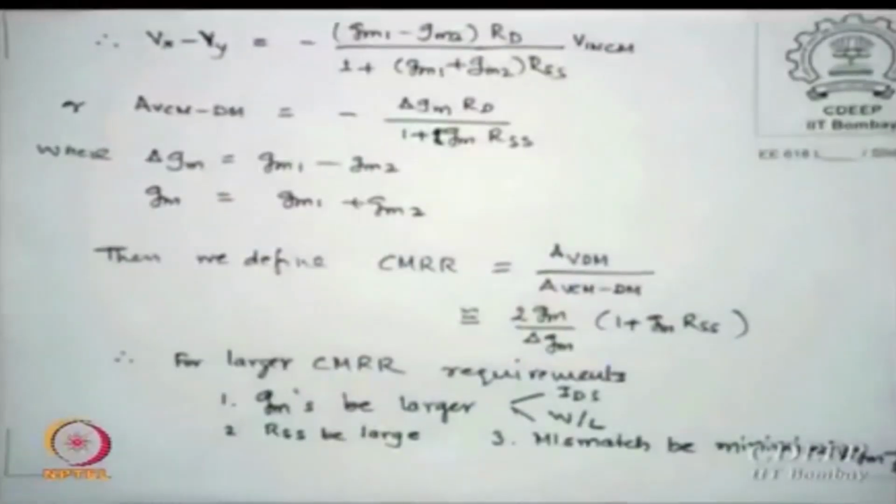So we actually solve it and figure out what it is. And another thing I keep saying, when I design something and I convert it to layout, which is one of the major outputs of any course on design, then the first thing we will do is extract the circuit back from the layout, the layout which I have drawn for the poly and every region, and then re-simulate that circuit, and you will be surprised that the specs with which you initially drew the layout do not match, okay. So you have to redraw or re-simulate, change something, redraw it, re-extract till they are close by,